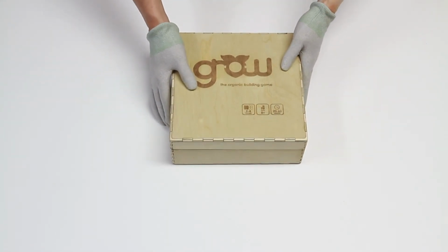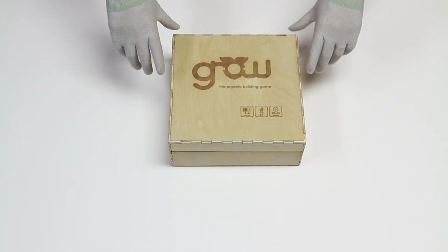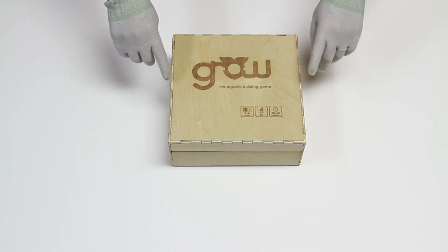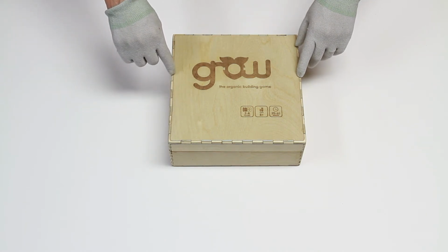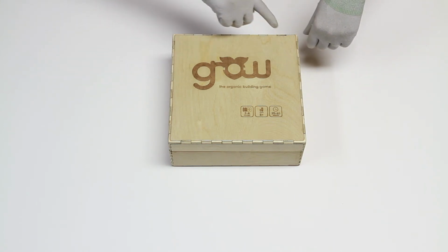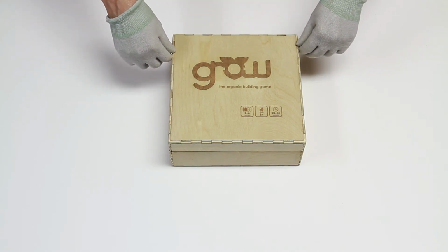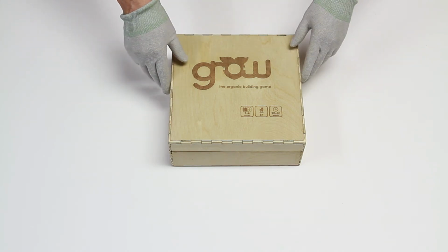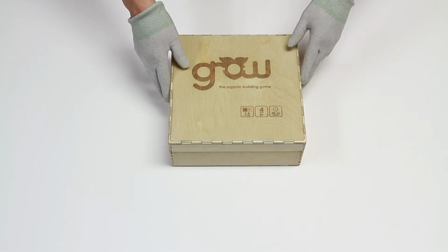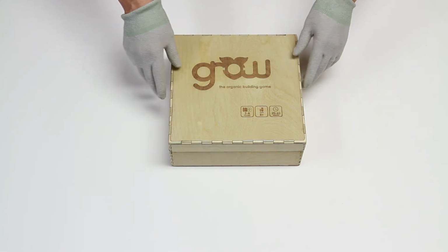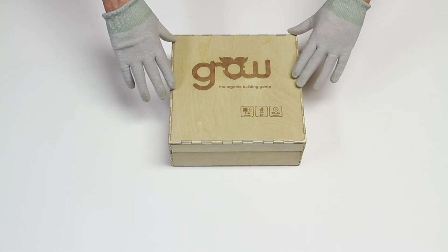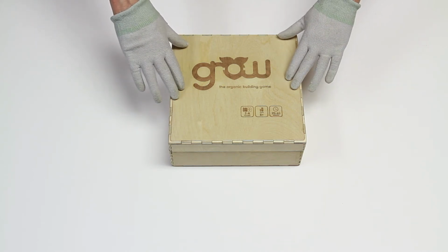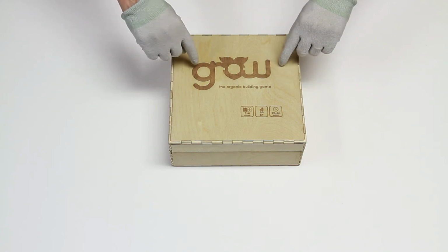Okay, so we went and we 1/4 round the edges. This material is plywood. We're hoping to remove the black, and we did that. There is a thin line, it's kind of the edge of the soot that's in the finger joints. A few joints aren't done. That might be something you could adjust with the routing mechanism you use. What we're going to do is, the next step is we're going to use a stain. If you use a dark stain, of course, that'll suppress the contrast. We're going to use a lighter stain that matches the pieces in this grow game.